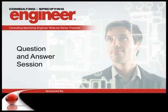The generator will put out current based upon the subtransient reactance in the initial cycles, and it'll go for a little bit, and then the PMG will kick in. And that'll kick in so that your maintained fault will not decay to less than 300%. It doesn't mean that your fault is 300%. Your fault is actually a lot more than 300% at the initial phase, but it'll decay to that point and allow your breakers to trip.